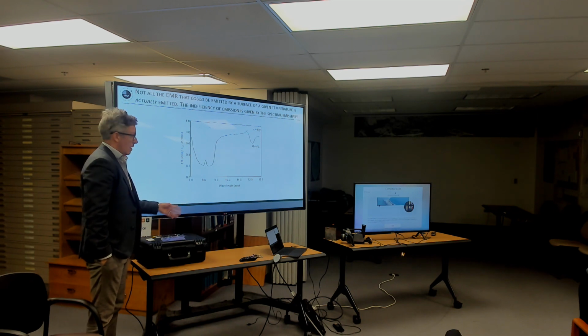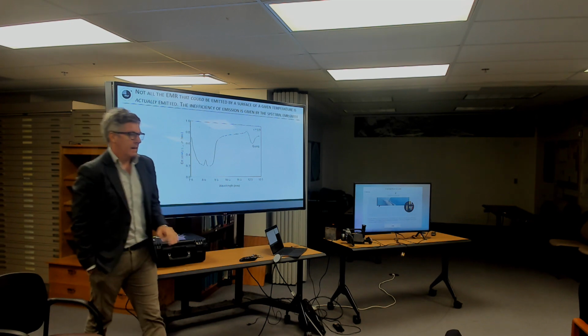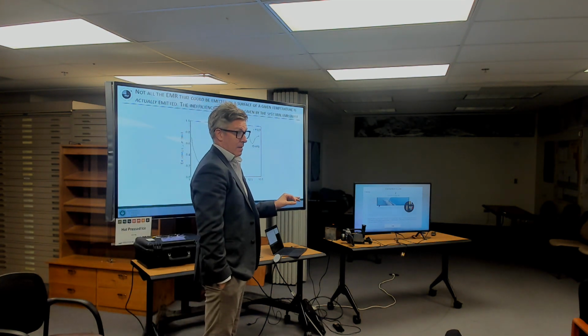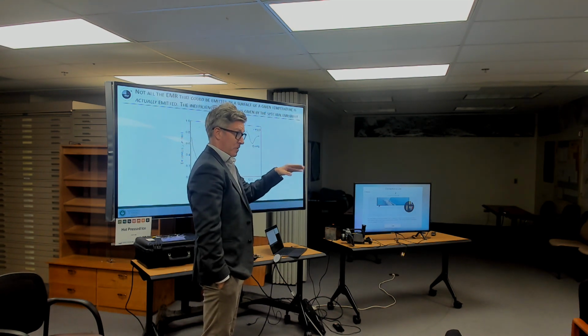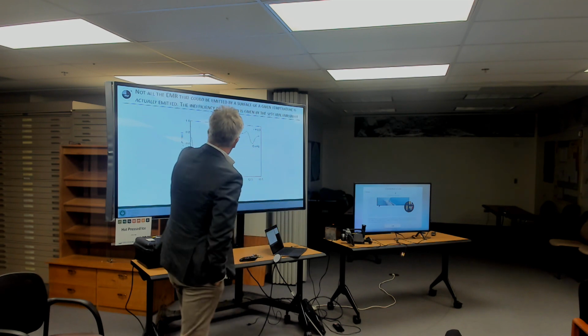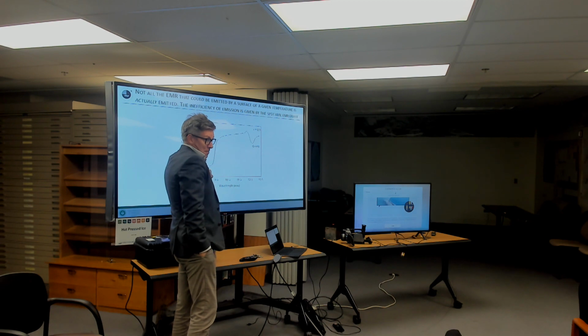So in these curves, high values of emissivity indicate that the material is very good at emitting energy at that wavelength. The closer it is to 1, the closer it is to black body performance. Where we have a trough, the material is not very capable at emitting light, and its behavior is far from a black body.